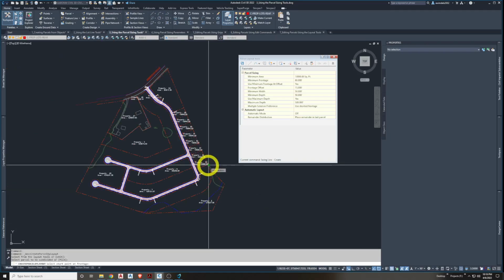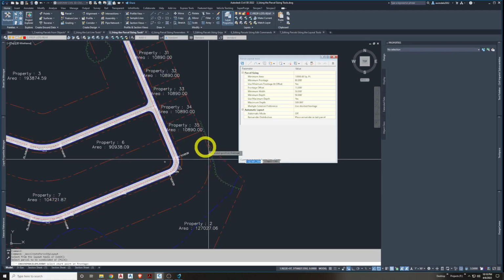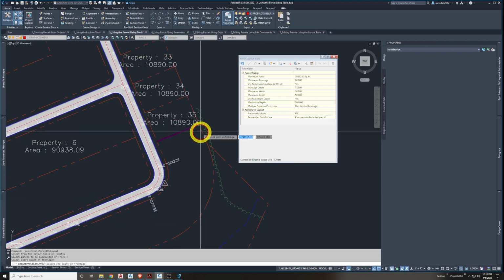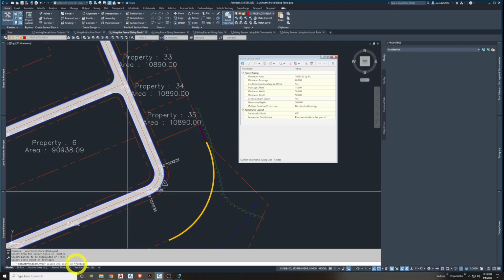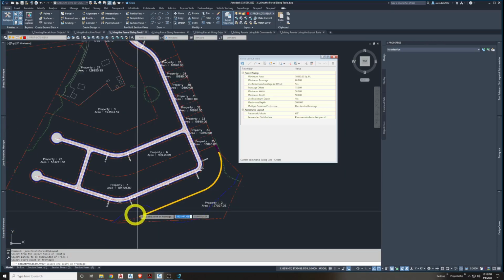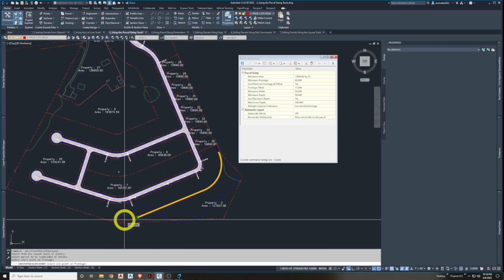And I zoomed in here to property 2. After clicking it, it said this is our point of interest. Let's click on this frontage. Pay attention to what this is saying. It said, where do I want to start? Now it's saying select an end point on my frontage. Well, let's follow this. Let's see if I can get it to go on the first try here. And we're prompted for the endpoint of my frontage.